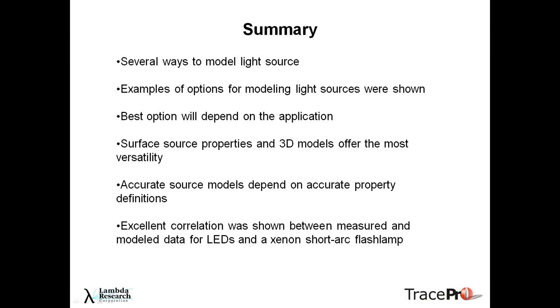We also talked about how accurate source models are really going to depend on accurate property definitions. If you don't have good property definitions, you're just taking really a shot in the dark. And then we showed some good correlation between measured and model data for both LEDs and, in this case, a xenon short arc lamp.